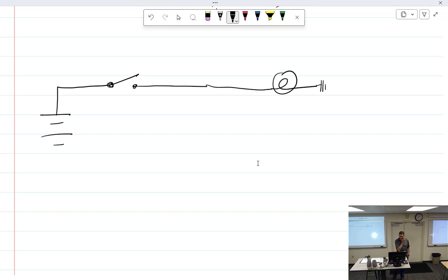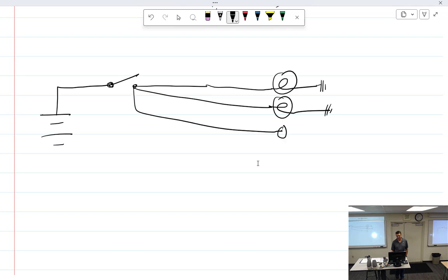How did the dash look afterwards? And so what was my problem with this? You put a ton of light on there that drew a ton of current. And I didn't want just one light, I wanted a couple of them. The switch can't handle that much current.